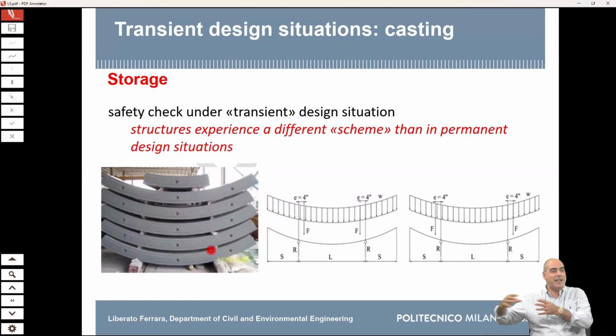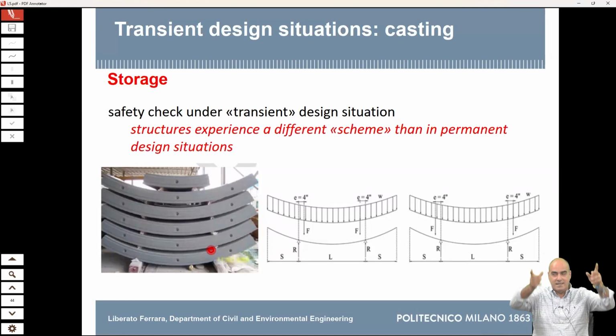There is then a retinue after that, and there is a train, and also there is a part which transports these segments from a stocking yard, which is nearby, just to the tip of the tunnel boring machine. And it's good to have all one segment transported in one carriage so that you have all the elements to complete your ring, because on that ring then when the TBM advances, that gives back the thrust to the TBM to advance.